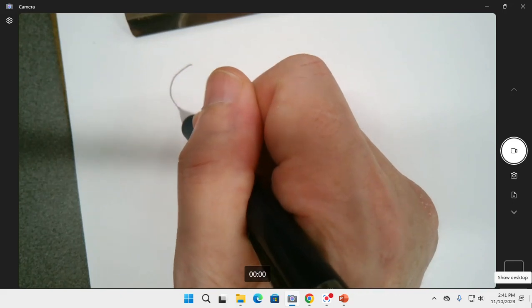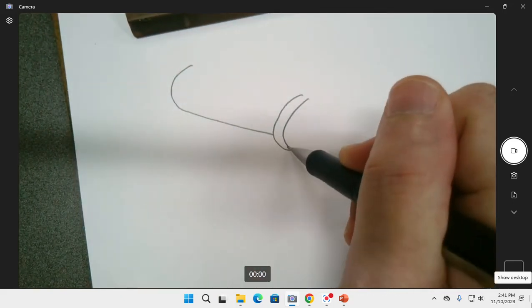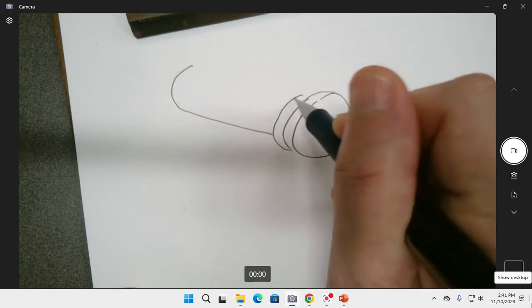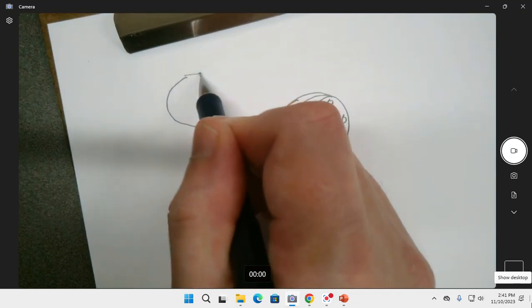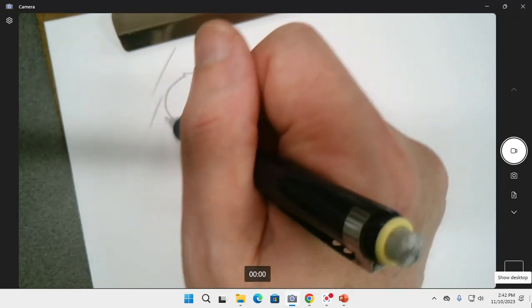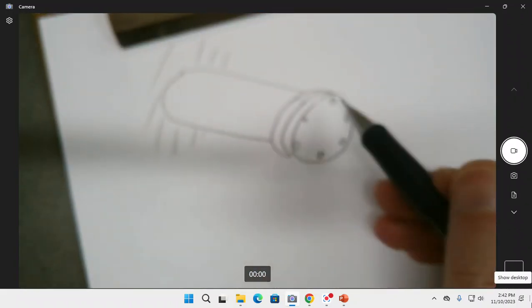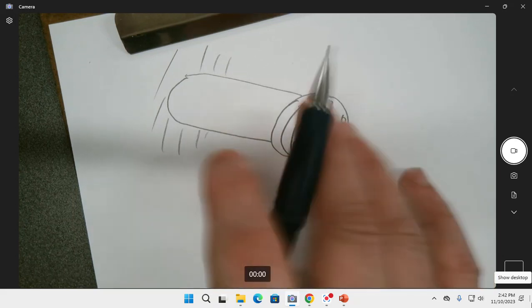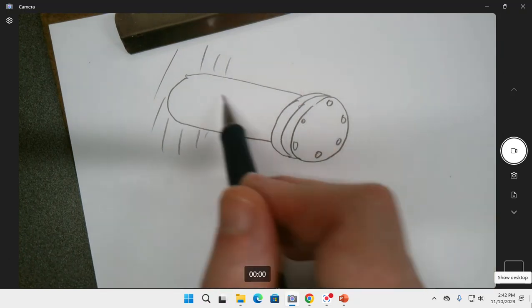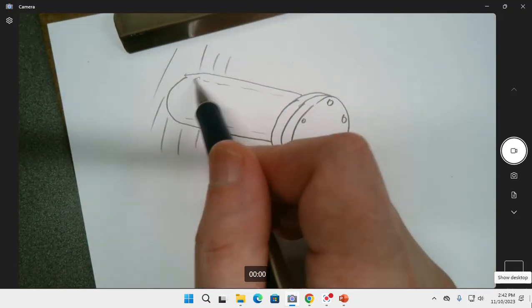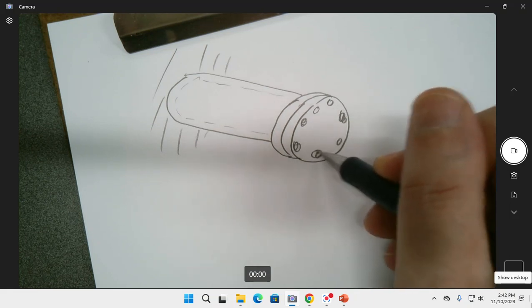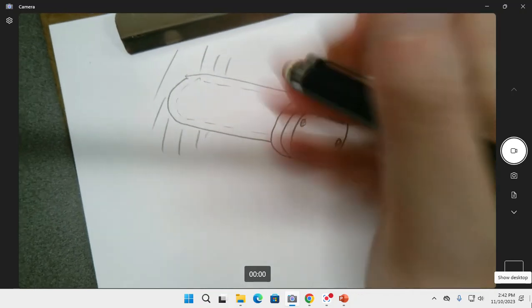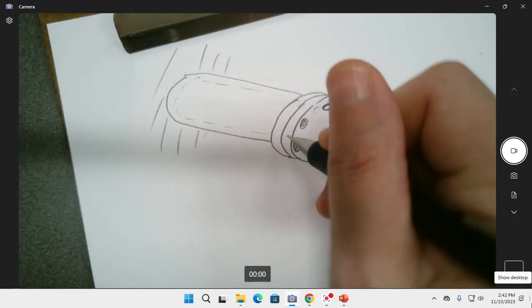So I'm going to invent a problem. This is dangerous, but let me try to pick out some values. Say you have something like a pressure vessel here. Here's a blanked flange on the end of this, with bolts holding it in place. This is cantilevered off, so this pipe is coming out of a wall or something, and we're holding this thing up. It used to be connected to some system, but now it just holds in steam or something. Let's not make it too thick, because we would like to use the thin-walled equations, since the thick-walled equations take more time. And these bolts are terribly patterned. This is a terrible bolt pattern, and OCD is making me add that bolt right there. Okay, so these are bolted in here.